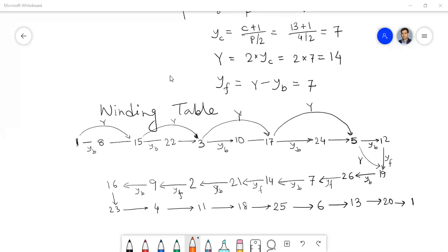You see the same similar machine, 4-pole 12-coil machine. If we go for wave winding, we can get up to 60 volts, and if it is a lap winding, we can go up to 30 volts. So lap windings are chosen for low voltage machines. And as there are more parallel paths, you will get more currents. In wave winding, only two parallel paths.